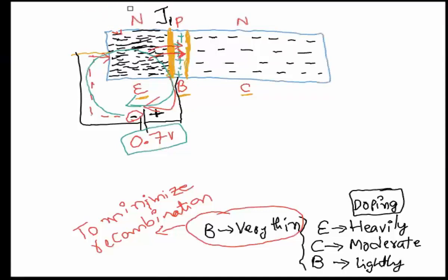So are we clear on that side? That's why usually on the base, all we need to make sure is you have either 0.7 or more than 0.7. And if you have it, we say the transistor is turned on. That's the requirement and must for an NPN transistor. The base must get a positive 0.7.